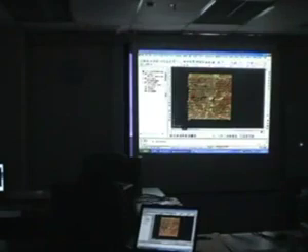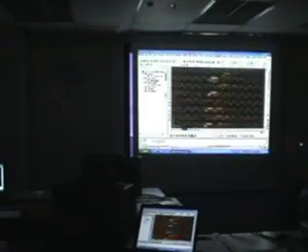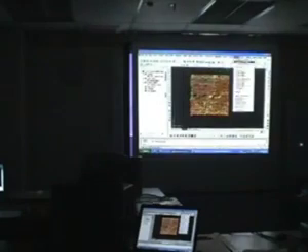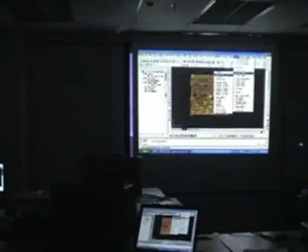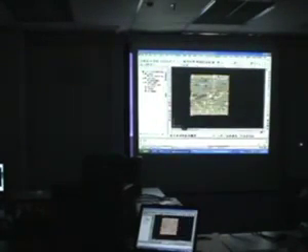At the moment you find there's nothing added to the drawings because in Desktop it's run on a project basis. So although everything has been updated, it's saved in the database, it's only loaded into the drawing on demand. Let's say now you say, okay, I can't see the triangles, I want to see what the triangles look like. So we just go to Terrain, Surface Display, and I'm going to use Quick View. This quick view basically lets us see the triangles only as a temporary preview. You can see the triangles now, but if I redraw, it disappears.